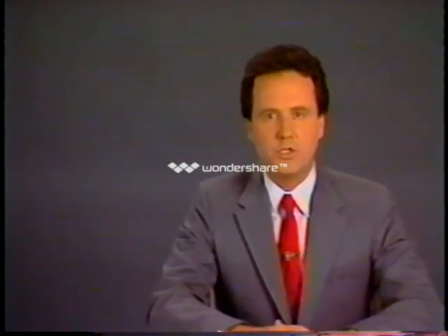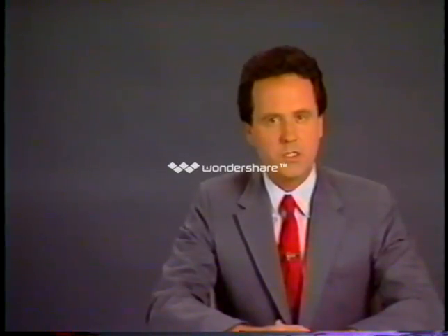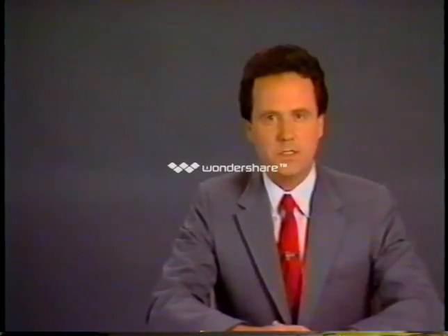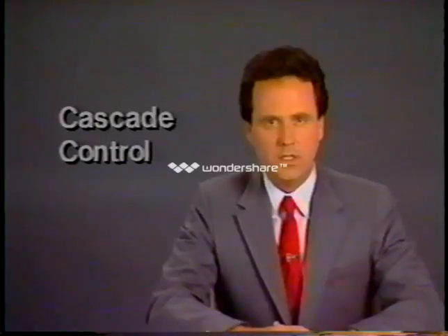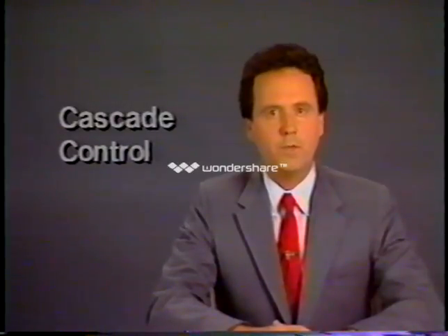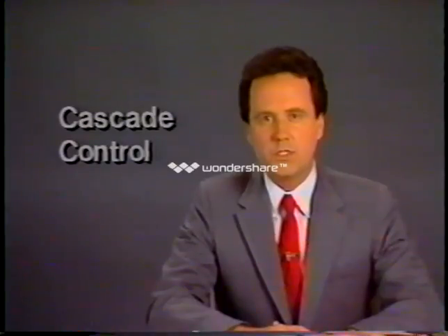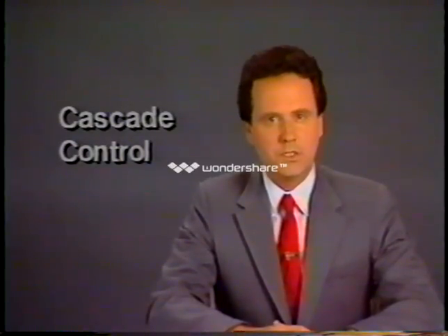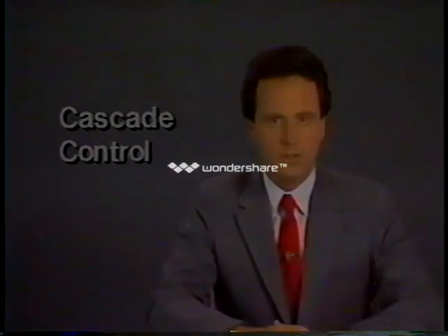In the second half of this unit, we will look at a control strategy used when a process is really 2 processes in series, functioning as a unit. This strategy, which is called Cascade Control, involves the use of a feedback loop within a feedback loop and can result in improved performance of the overall process. Cascade control is sometimes used as an alternative to feed-forward control, which will be discussed in the next unit.